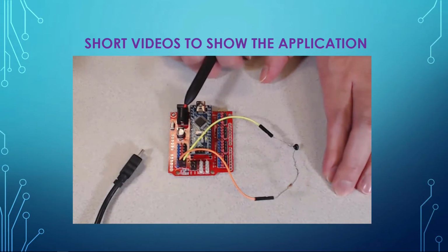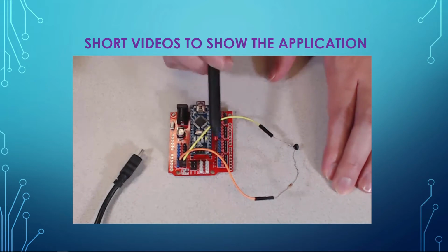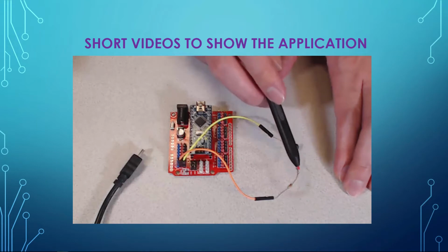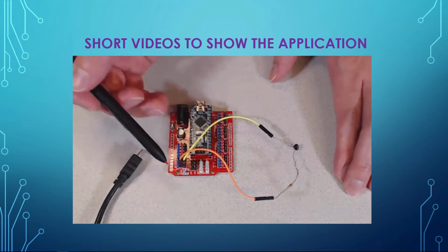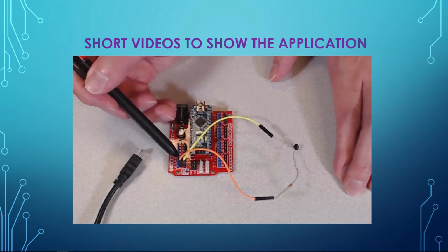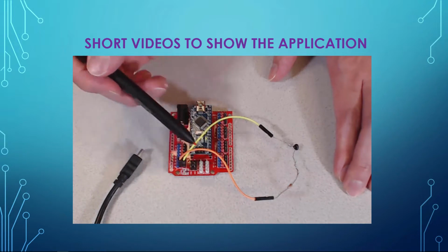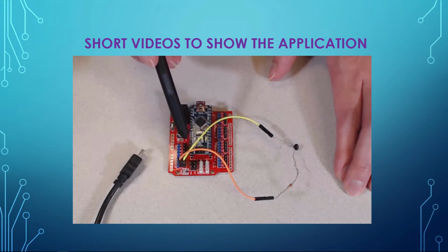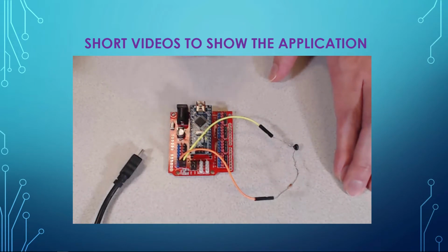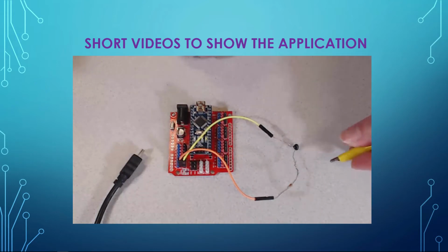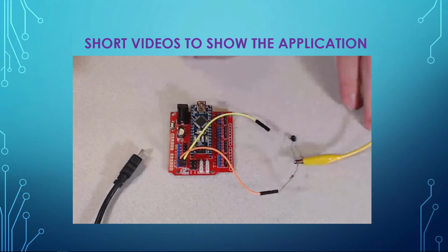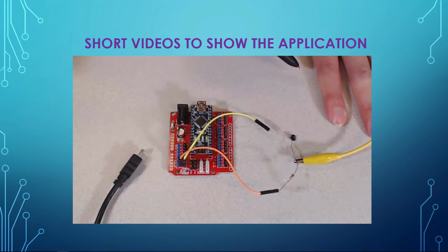As we all know, resistance cannot be measured directly, and this is why we need to use this voltage divider circuit. As you can see, these two resistors are connected in series with a power supply coming out from the red pins here, going up and then through this resistor to the temperature sensor and then back to the ground. So if we take a voltage measurement here at this node, then we can measure the voltage difference.